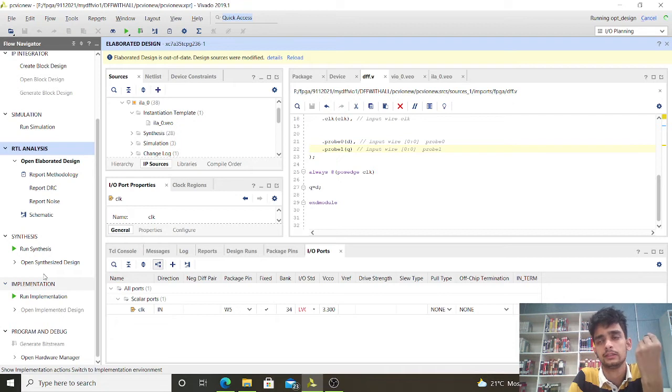If we increase the drive strength, the current is increased, so the delay is less, but the area is increased. It automatically matches the instances which are already there.